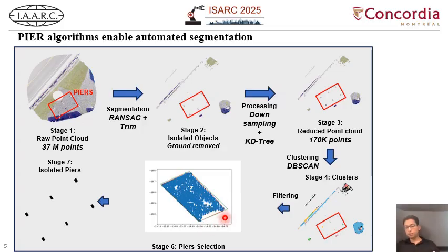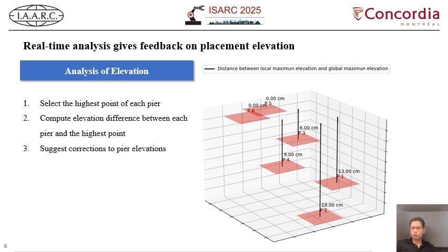And so if the difference between the minimum bounding box rectangle and the actual contour is small, it means we have a pier. So we retrieve the cluster, and at the end we end up with our 6 clusters, which are our 6 piers. So after successfully retrieving the pier foundation from the point cloud, we can start the analysis process.